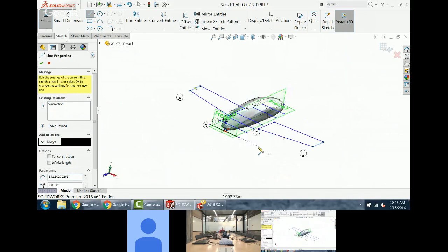What it'll do with these shapes is it will extrude them as surfaces. So you do want to make sure that you don't have crossing geometry. You can't have a line on top of a line when you're doing this type of thing, because it's going to want to take that and extrude it as a surface. So it's got to have valid geometry for creating surfaces.